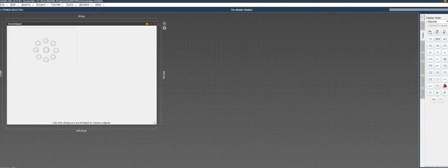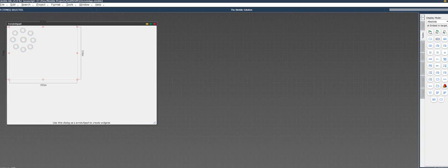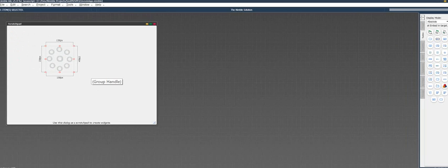Oh, but we made one mistake. We pasted into the frame, but it's not embedded, it's a group. So let's repeat that. We'll Ctrl X to cut it out of the frame as a group, and then turn on the embed target property. Once we've turned that on and then paste it in, it is now embedded in the frame. We'll position all of our icons snug to the upper left corner, change the size of our frame so that you're not wasting real estate. And that basically is the bare bones of our custom widget.